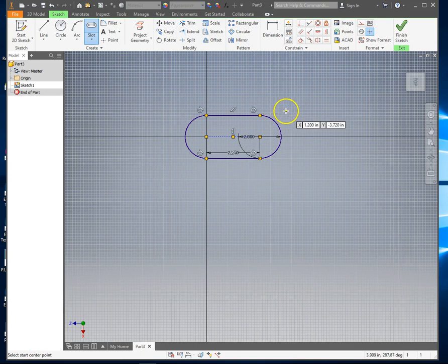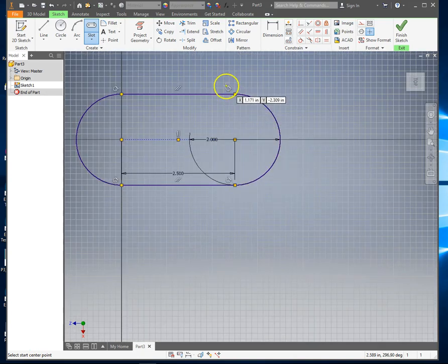added with this slot command. We got tangents, so we got 4 tangent locations, parallel locations, horizontal locations, sizes. So a lot of things that were incorporated in that particular command. So I could put some other shapes in here, the 2 center circles. I could decide where I'm going to cut this off, and then I can extrude that. That's all I can think of for these labs.